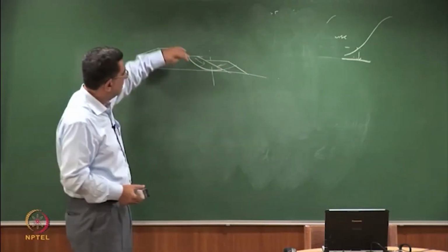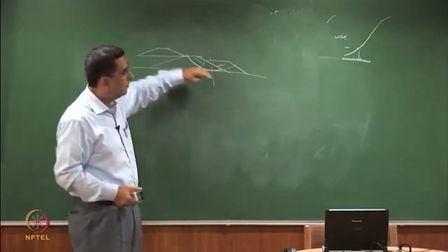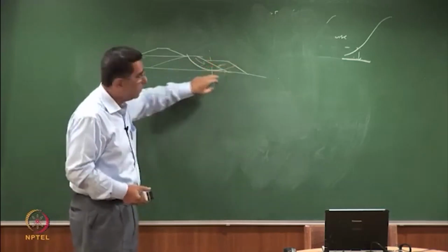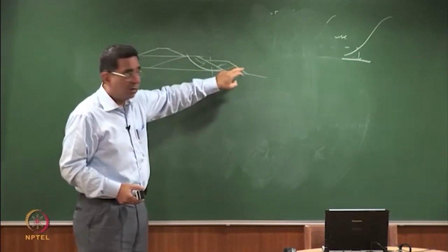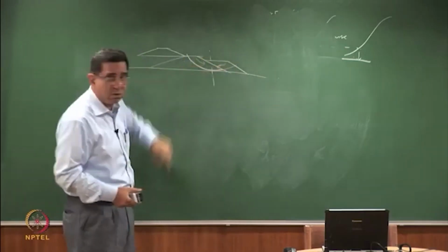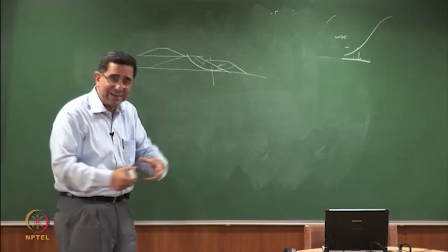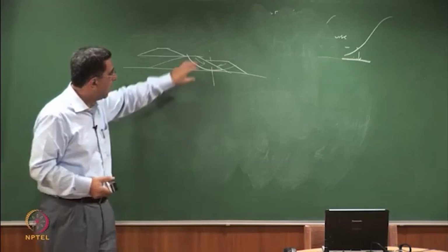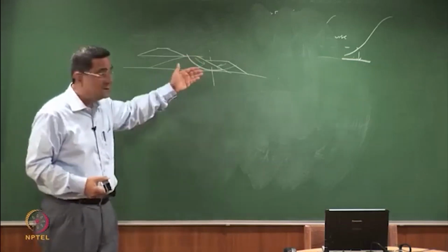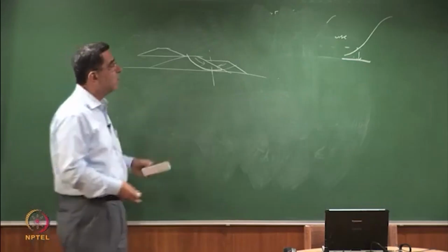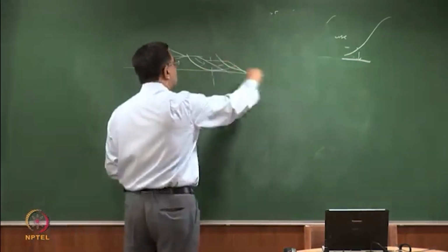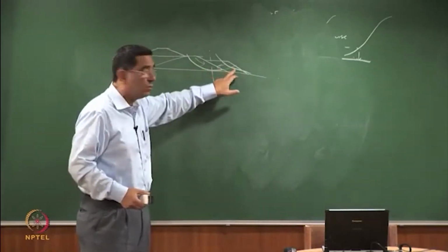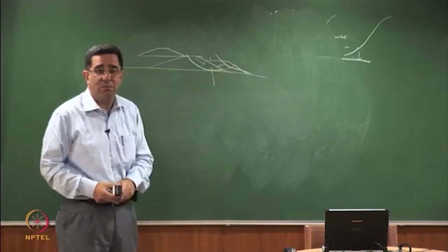Are you appreciating this? This was the original failure surface. This was the downward force. Now I have put this stabilizing berm. If I extend the original surface, then this force is acting this way because the slope is on this side. So the stabilizing berm is acting against the driving forces of the earlier mass of the embankment. So this increases the factor of safety. After the stabilizing berm is put, the new failure surface will be here. This will give you a lower factor of safety, but since there is no phreatic line here, it will give you a factor of safety which is above 1.5.